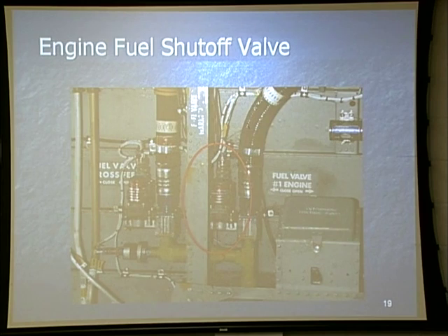Okay? Now, why do you look for the engine shutoff valves to be open? Because the fire pull handles are in. There's no more tricks to that. So why am I looking for the crossfeed to be closed? The switch is off. It's that simple.